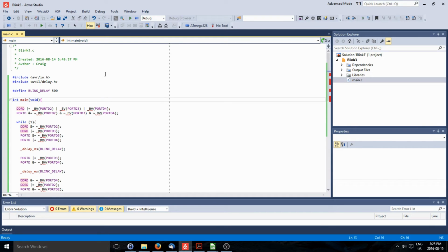And what that does is it will set those 3 bits, only those 3 bits in that register, and then I write it back. So whatever the other bits that I didn't set, I didn't affect, they remain unchanged, and I just simply write them back into the register, and nothing happens to those ones. So I'm only affecting the 3 that I want to affect.